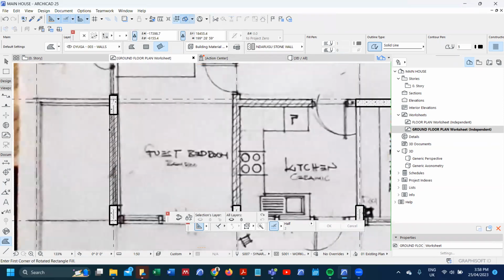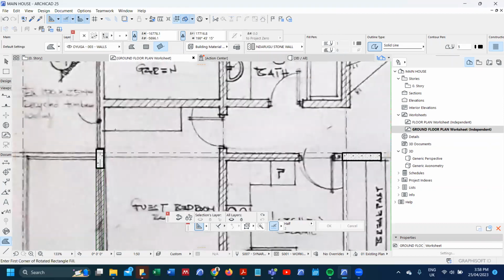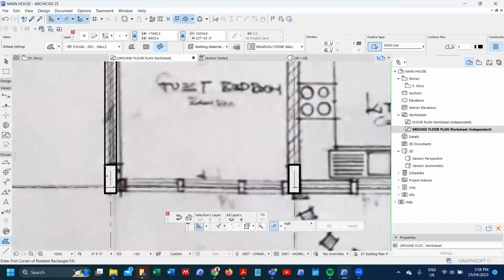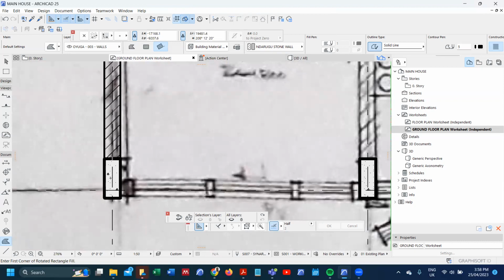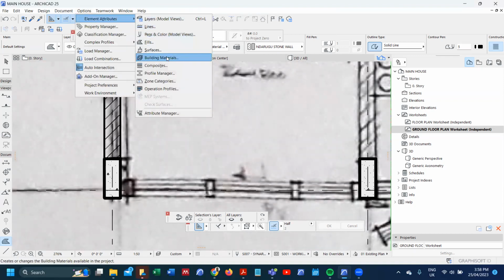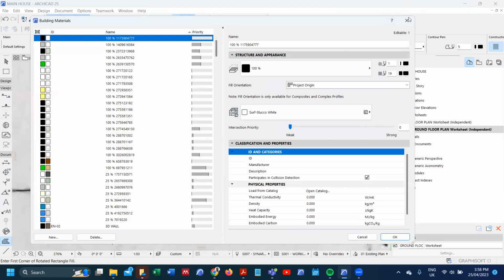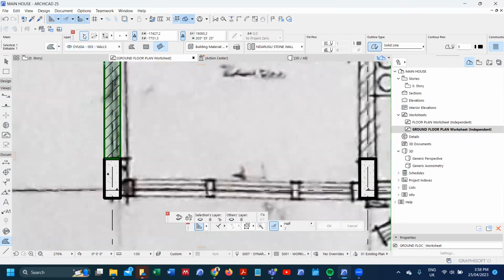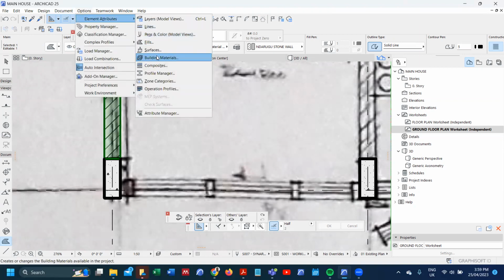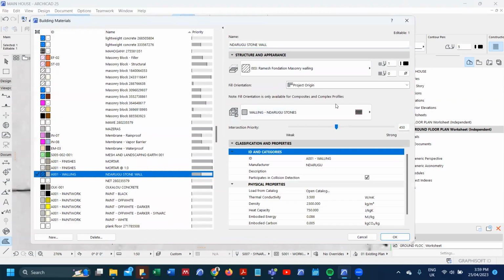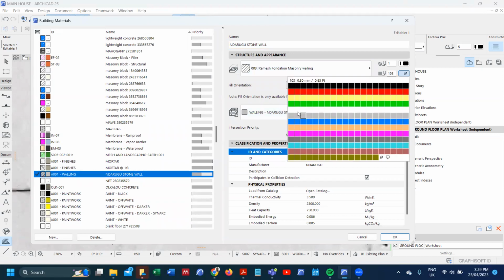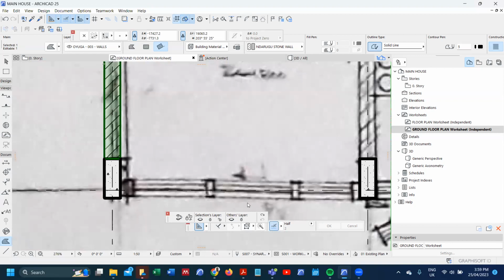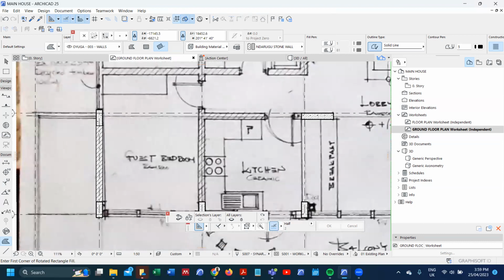Easily place that one. Okay. Now, one thing you'll notice is that our walls are transparent while our columns are not. This is just a setting of the building material. So let me select it. This is my wall. Let's just select and see the settings of the building material. As you can see, it's made transparent. We can make it have a white background, and if you do that, it will just match the tone of the column. So you can always toggle those settings.